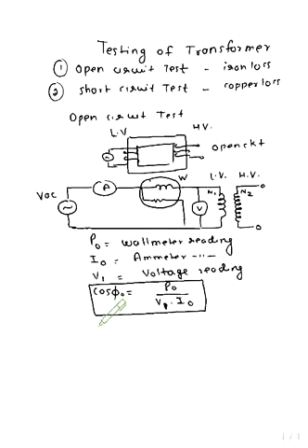Similarly we can find the two components of no load current. The no load current has two components: I0 squared is equal to Im squared plus Ic squared. Im is the magnetizing component of current, Ic is the core loss component.